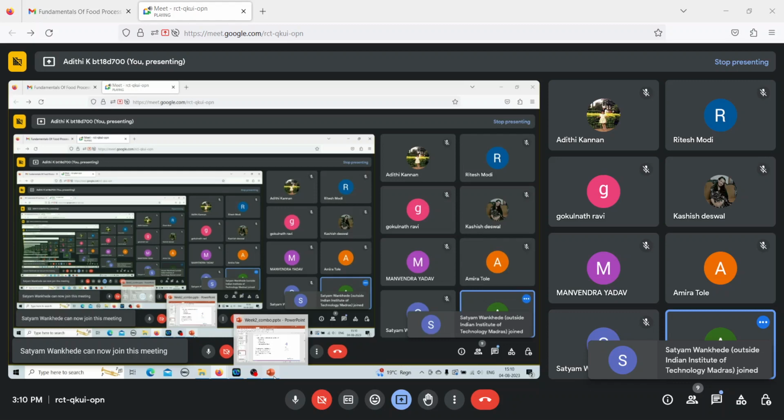Second thing is that you can keep rotating it for as long as you want. So you can do a time dependent study as well. So this viscometer is also used for time dependent fluids, that is the rheopectic and the thixotropic fluids. So these rotational viscometers have two purposes. One is to control the amount of shear rate that you give, and second is to study the time dependent behavior. So both can be done with these rotational viscometers. So the answer here is you can study non-Newtonian fluids, especially shear thinning fluids, and you can study the time dependent behavior of the fluid.